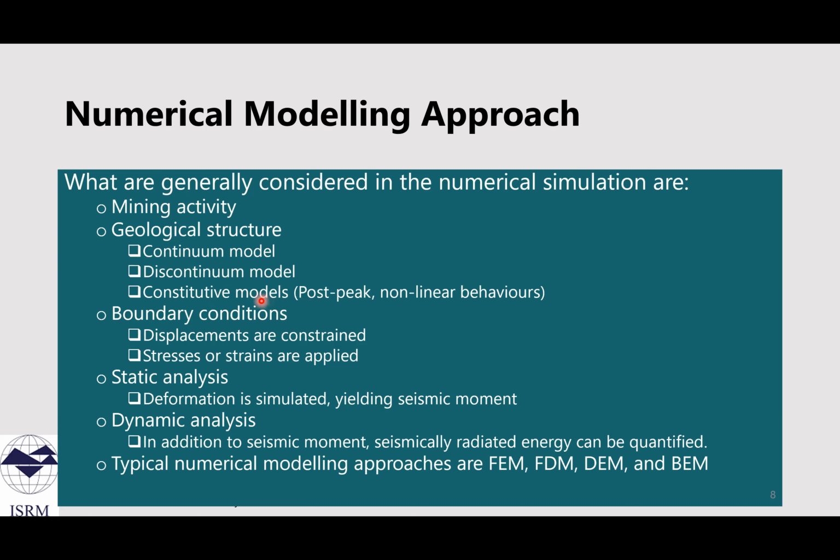The middle one is a model in the framework of the discrete element method. In this model, I incorporated the fracture network to examine the fracture network induced stress concentrations. And the right one is a mine-wide model that incorporates several geological structures, like dike and fault. This model allows us to examine the stress change in the extensive regions surrounding this ore body. The sequential stope extraction was modeled, and the mining-induced stress change was investigated for this fault and dike.